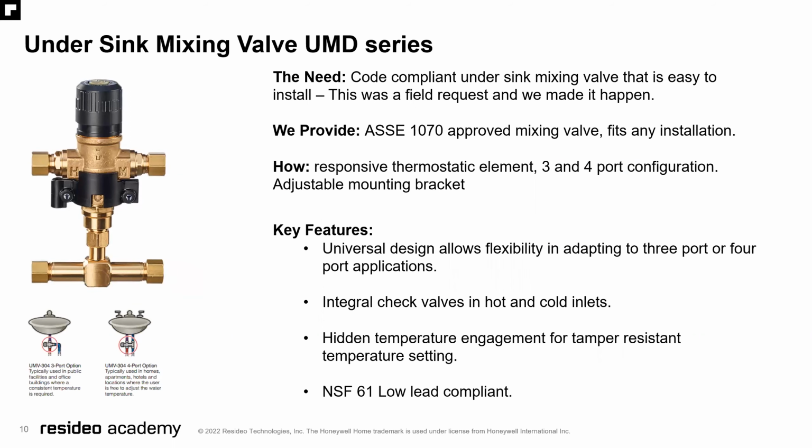We also have the undersink mixing valve, the UMD series. The ask from the field was a code compliant undersink mixing valve that is easy to install. This was definitely a field request, and we definitely made it happen. To provide an ASSE 1070 approved mixing valve, lead-free, that fits any installation.